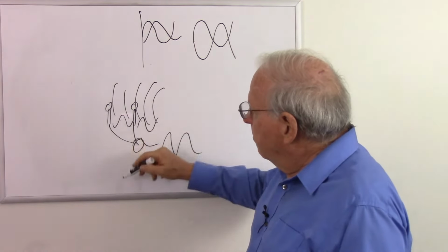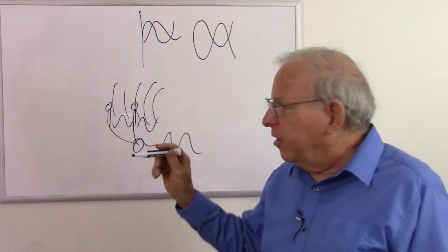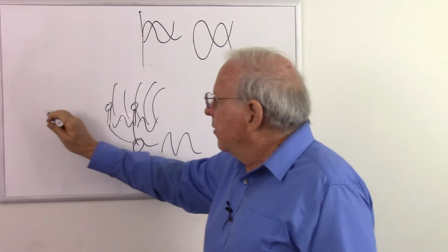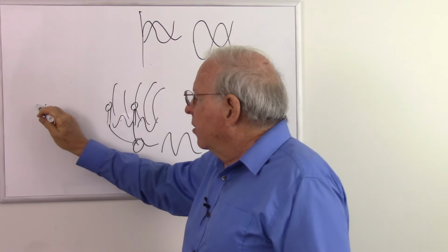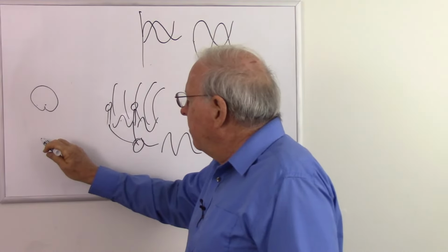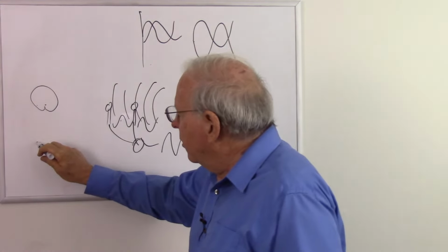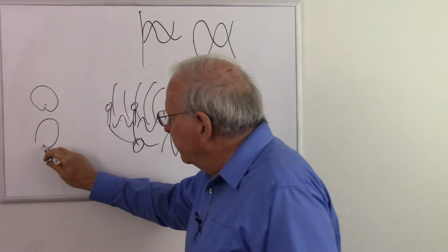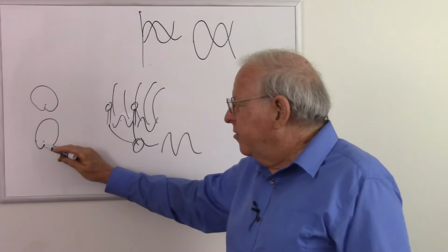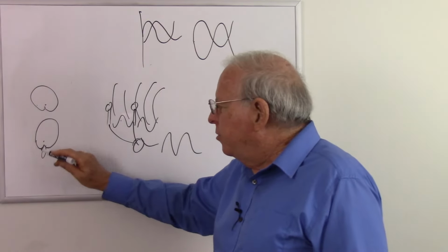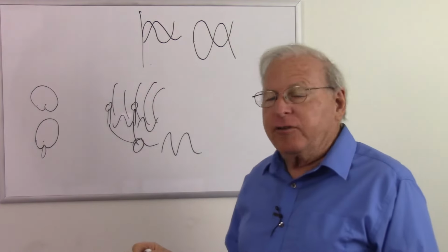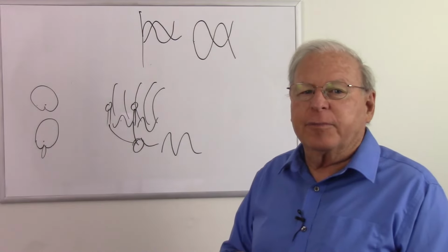It makes it basically a bidirectional microphone, unless these are cardioids, which means they're not sensitive to the back but sensitive to the front. And that increases, well, it's going to do something like this. Here's our cardioid shape, but here what we get is probably, I've never tested this, a bigger lobe to the front. I'm just going to draw it as a bigger lobe. So there's the microphone. More sensitive to the front, less sensitive to the back. We might get a bit of a lobe to the back when we do this. I don't know, but that's a possibility. But we're going to get more sensitivity to the front if we use two microphones in this particular fashion.